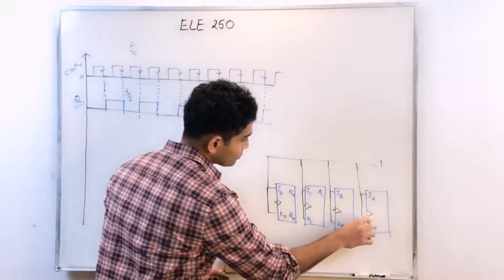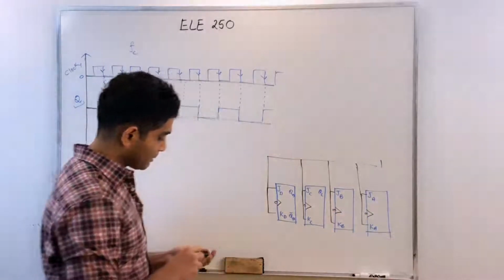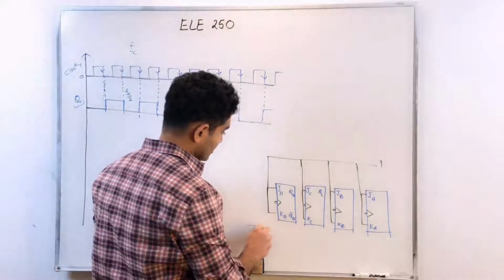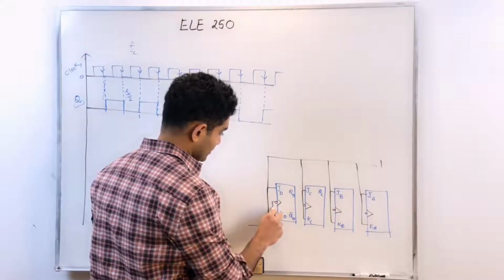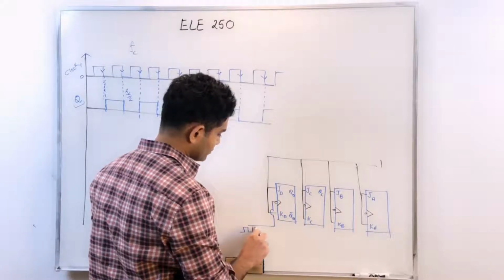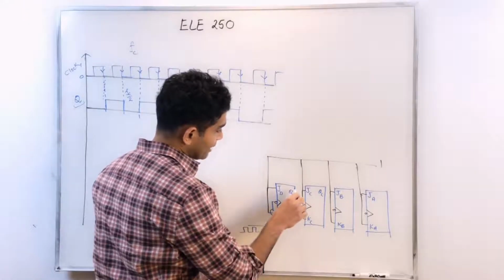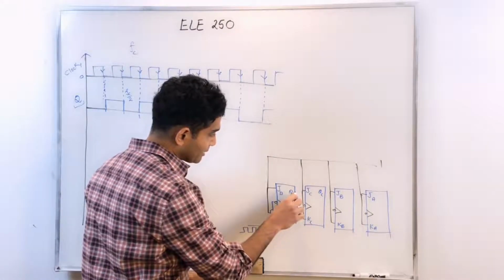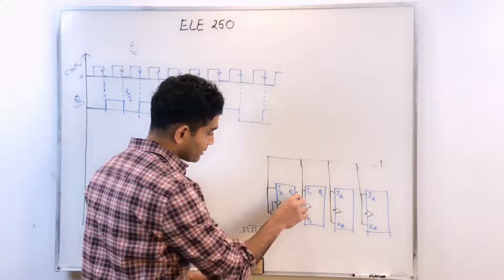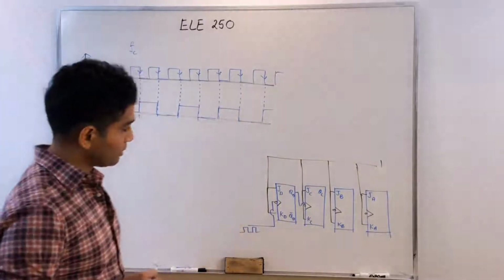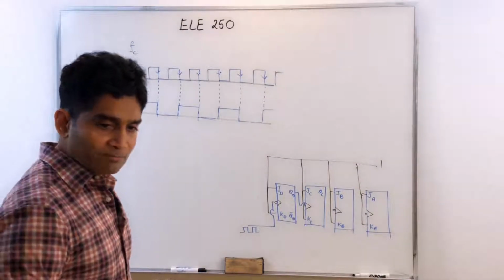So what I'm going to do with the enable inputs is that I will apply the master clock to the first flip-flop. That's the master clock, and see what happens now. And then for the clock for the second flip-flop, I will take the output of the first flip-flop and apply it as an input to the enable input of the second flip-flop.